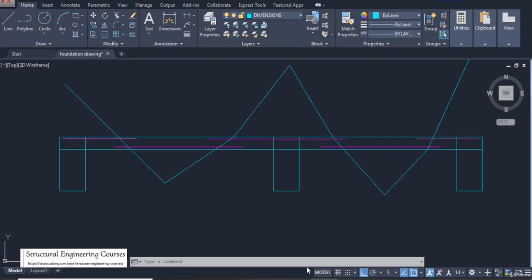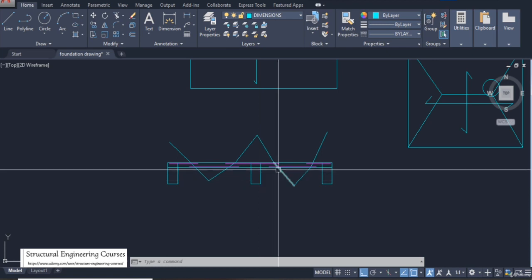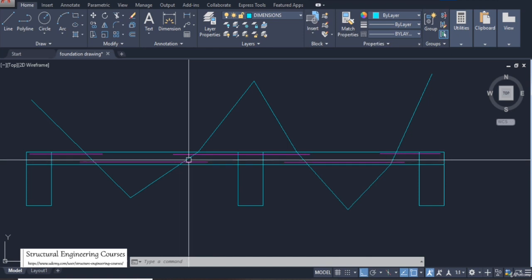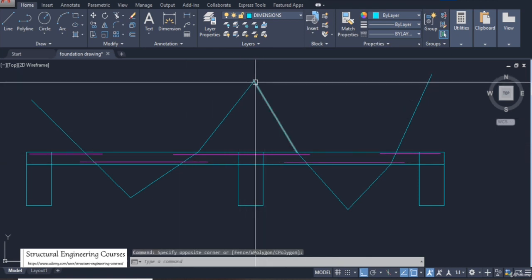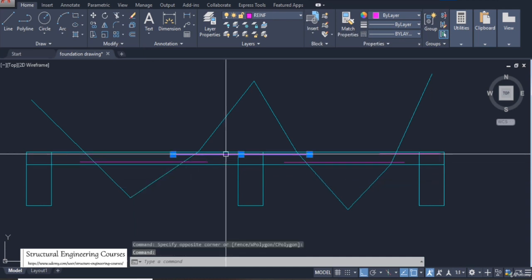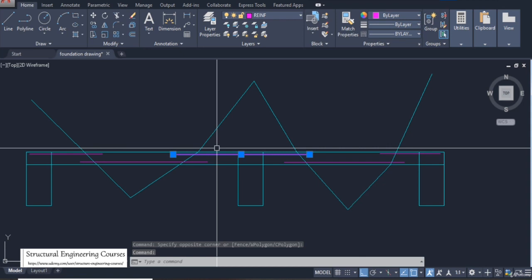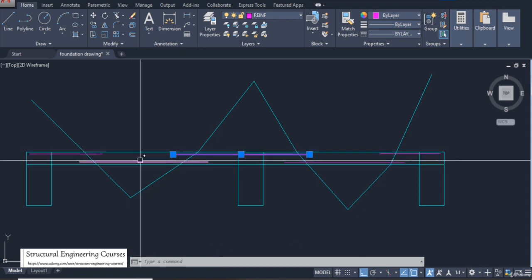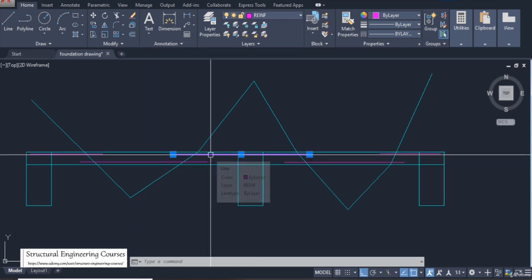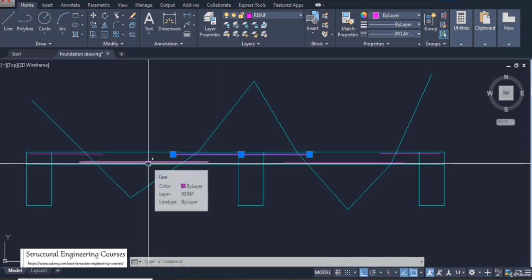Basically, let me explain this concept to you also, because this is a very important concept. In 100% cases, it does happen that this bending moment value is much larger than this bending moment value. So for top reinforcement, the area of steel requirement will be much larger as compared to the area of steel requirement for the bottom span. So if you see a drawing in the future which showcases that the top reinforcement for a slab is larger than the bottom reinforcement, then that drawing is correct. You don't need to worry about that.